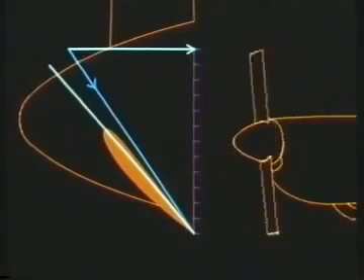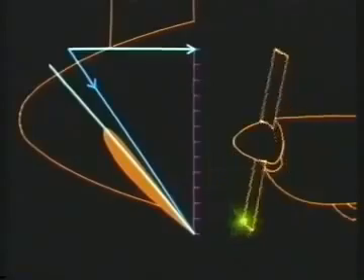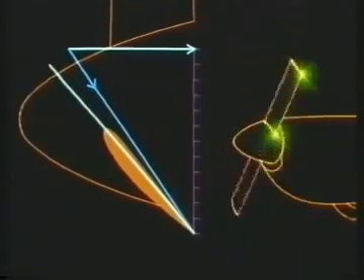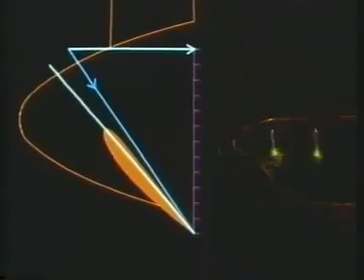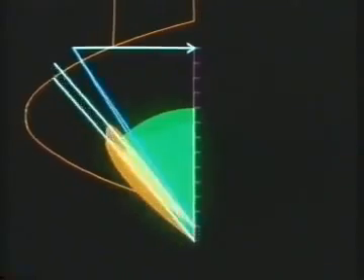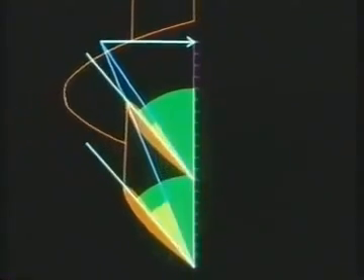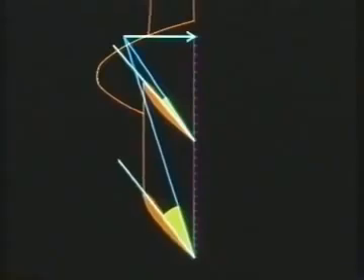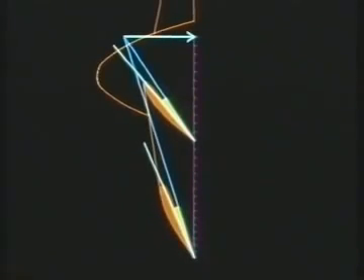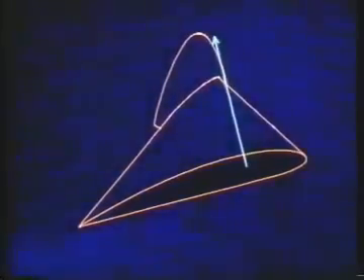The rotational velocity at the blade tip is faster than near the hub. And if the pitch remained constant, the angle of attack would increase towards the blade tip, possibly causing it to stall. So the blade is twisted to maintain a constant angle of attack. This is a fixed pitch propeller. It generates a total reaction in the same way as a wing.